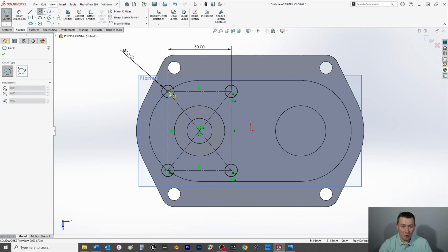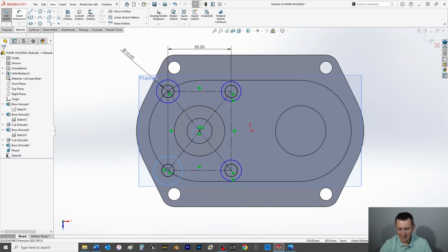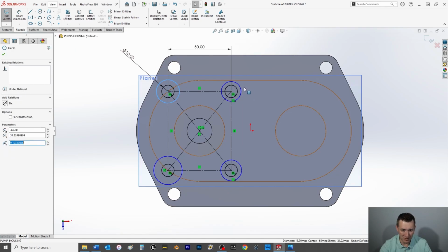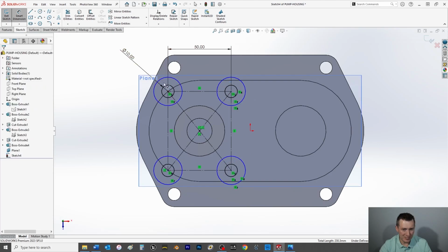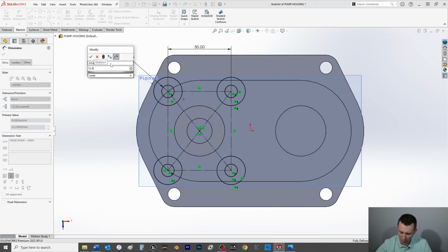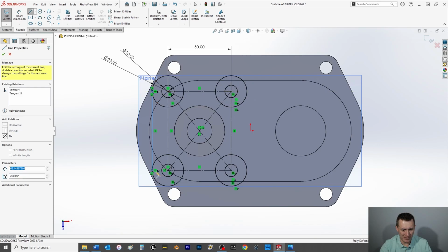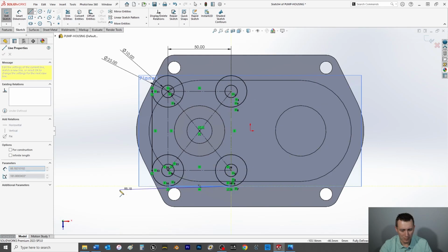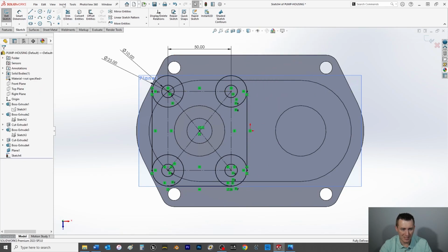And then we need to make our radial references, which are these large ones, just like we made in that first sketch. Lovely. Now these are 12.5 radius. So first, make them equal. Like such. 12.5 times 2. Then we're going to make some lines to complete the outer edges of this flange. Like such.